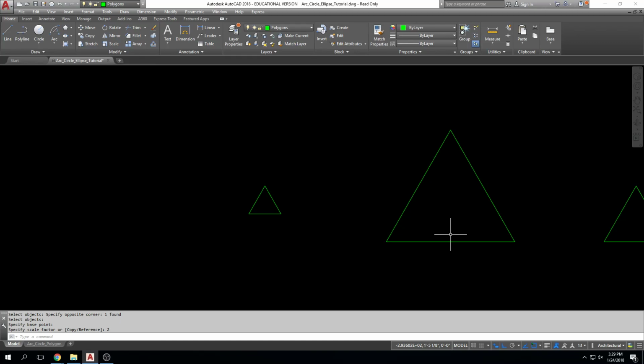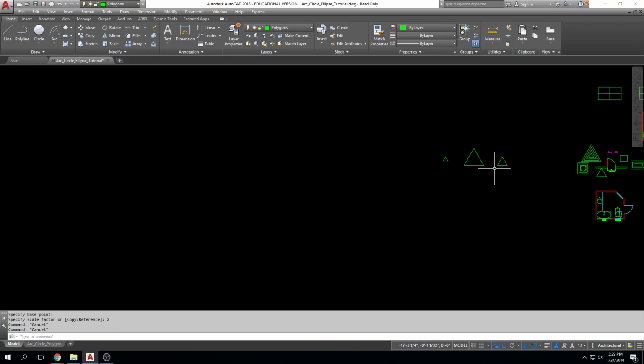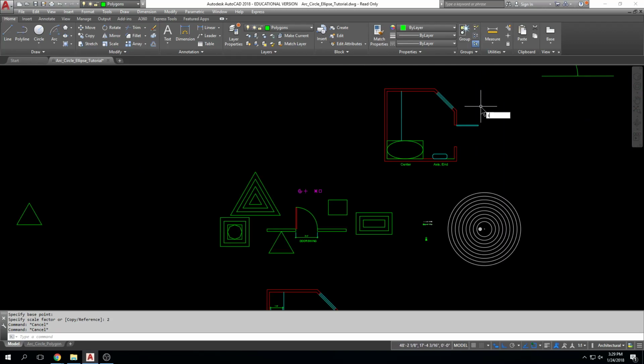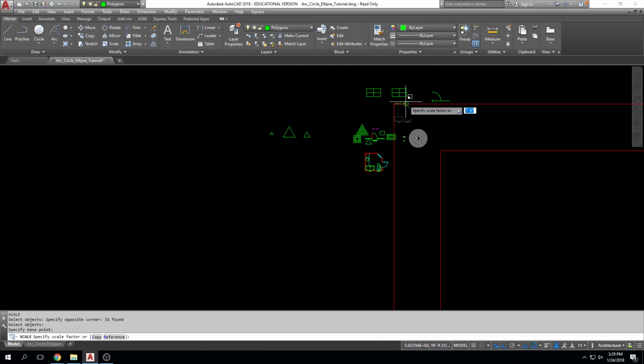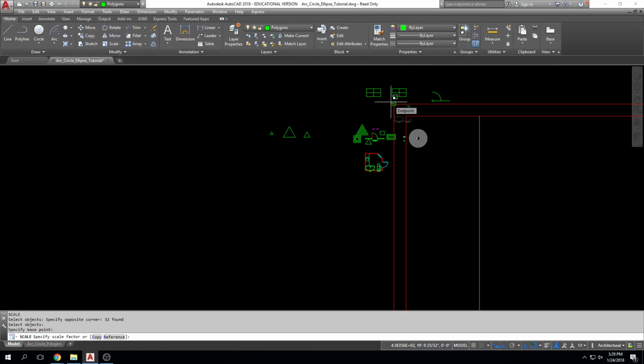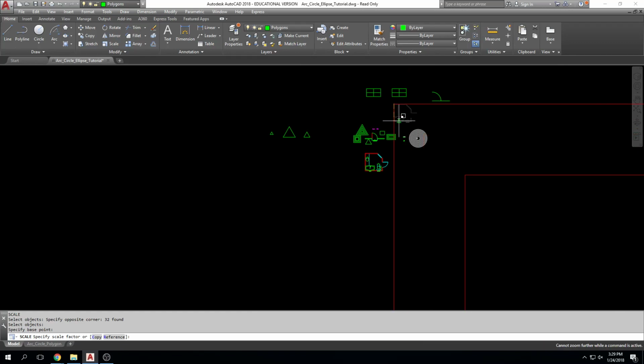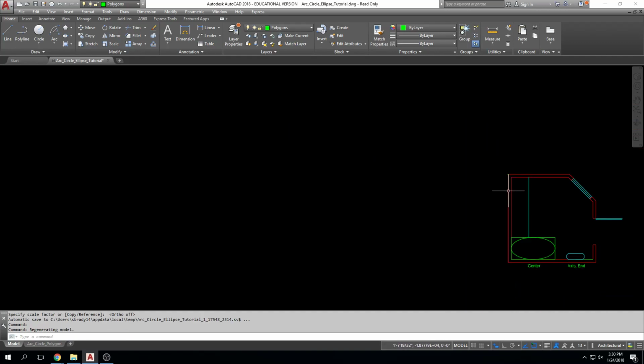So what might have happened is you did this. If you grab this, you type scale, enter. You grab this, enter, right? You clicked, and then if you start moving your mouse, it makes it extremely large, right? It's just giving me a preview, but the preview is very large. I can't really tell you why it goes so big or so small, right? But it starts to give you a preview. And if I move my mouse out, sometimes it makes it smaller. And if I move my mouse in, you see how it somewhat grows. But if I were to click right now without inputting a number, I'm doing a graphic scale. So if I click, it sets that scale to make it gigantic.